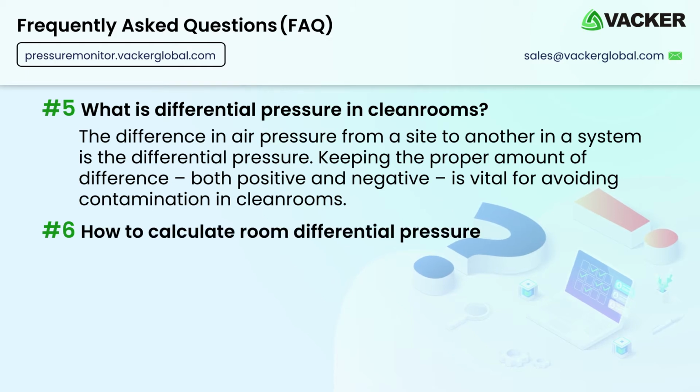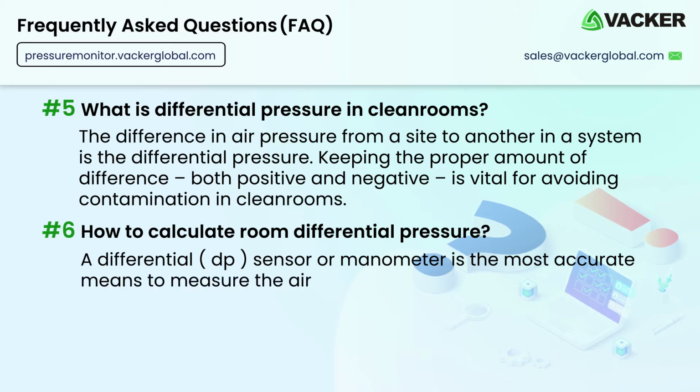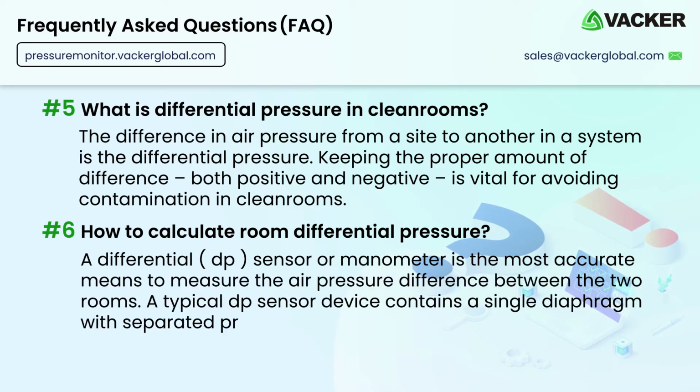How to calculate room differential pressure? A differential pressure, DP, sensor or manometer is the most accurate means to measure the air pressure difference between two rooms. A typical DP sensor device contains a single diaphragm with separated pressure connections on both sides.